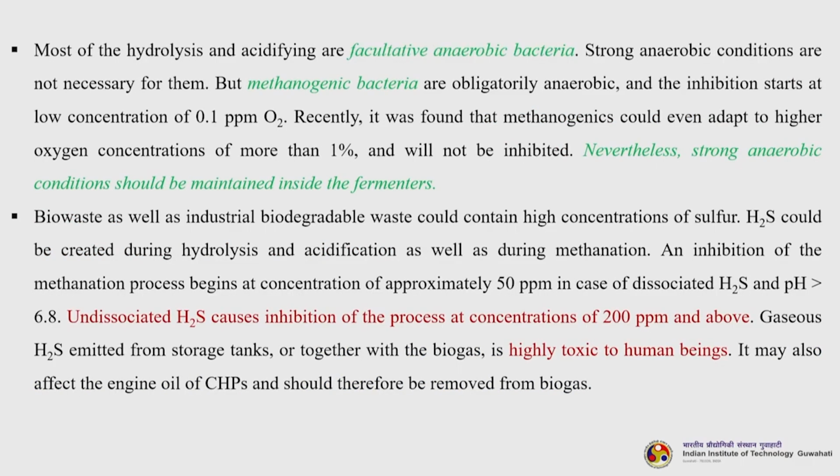So, most of the hydrolysis and acidifying bacteria are facultative anaerobic. Strong anaerobic conditions are not necessary for them, but methanogenic bacteria are obligatory anaerobes, and the inhibition starts at a low concentration of 0.1 ppm oxygen. So, it is very low, you can understand how sensitive these methanogenic bacteria are. Recently, it was found that methanogens could even adapt to a higher oxygen concentration of more than 1% and not be inhibited. Nevertheless, strong anaerobic conditions should be maintained inside the fermenters at all times.